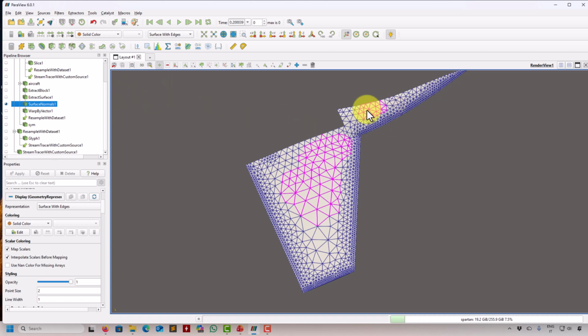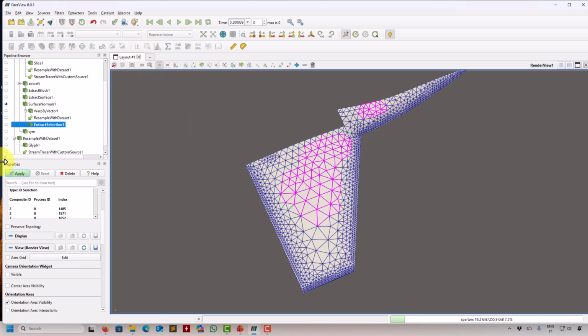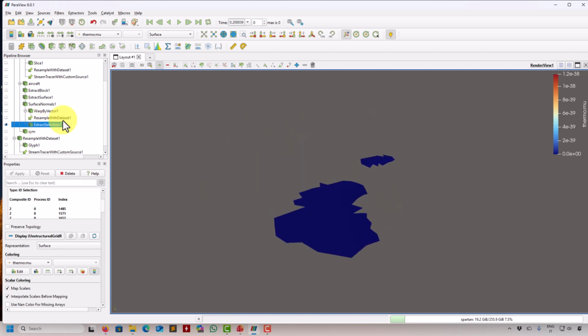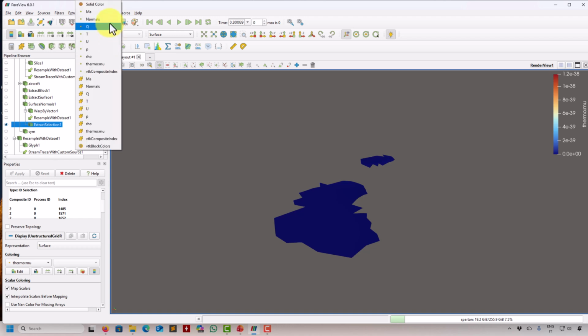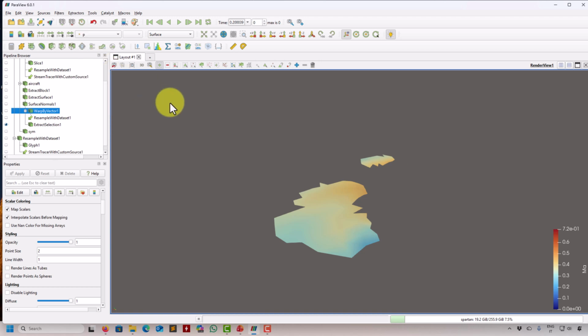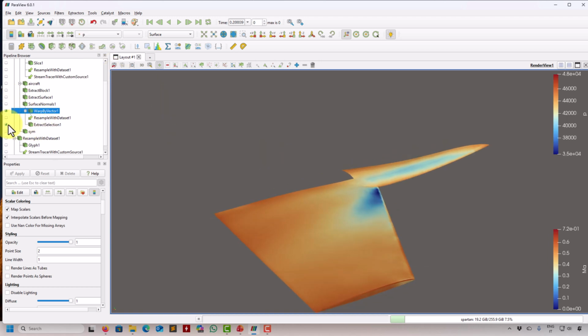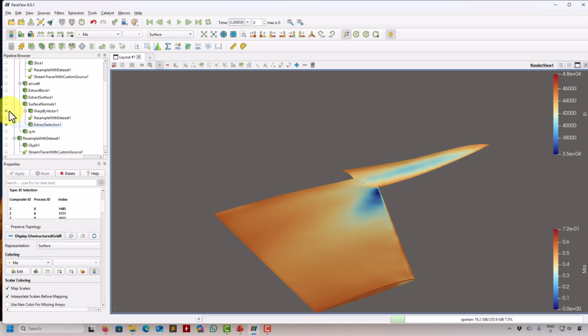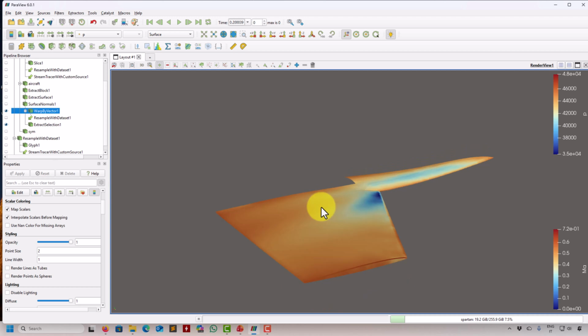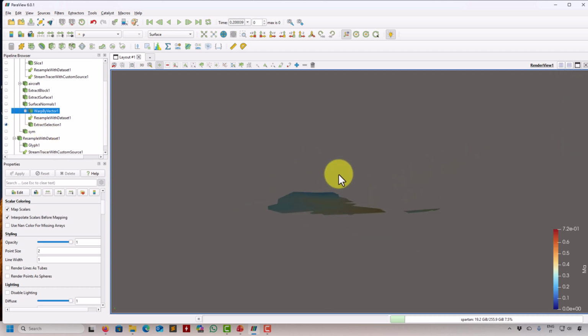Remember that you select that one. I can click here and extract that selection, and that is a completely different dataset. And on this one you can plot something else. So you have the Mach number, and here I can put my pressure, and you can plot it there. You don't see anything because you have it on top of that one. What you can do is the trick that I showed you: shift it, moving away using the normal. So always compute the normal and have it, and you are all set.